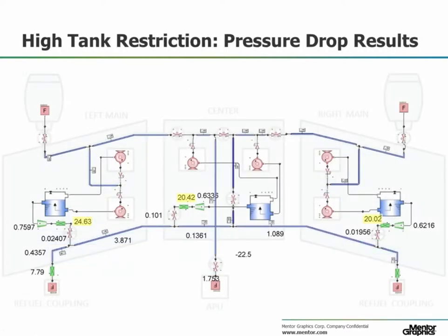After increasing the loss coefficient of the component from 10 to 50, our pressure difference results climb significantly, but are proportionally closer together. With a fixed volumetric flow rate boundary condition coming into the model, this may give us the more balanced flow we're looking for.